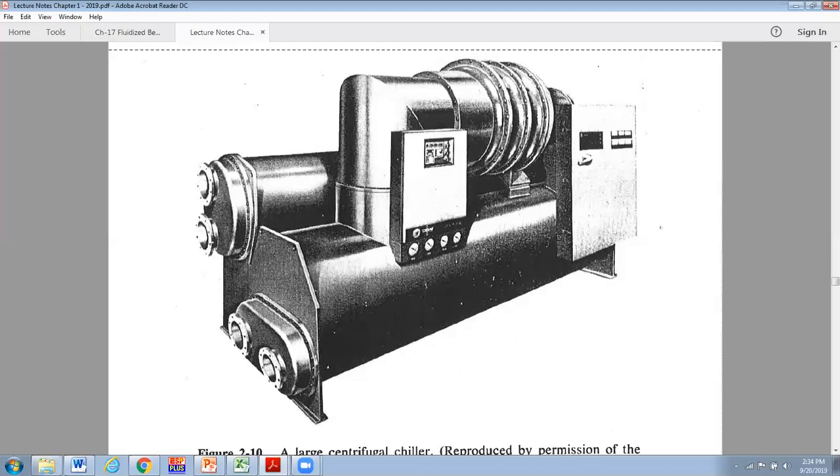And they're pretty good size. They can be really large. They can be much taller than a person. Smaller one, maybe not, 100 tons. The smallest centrifugal chiller, don't know exactly. I'm guessing someplace between 50 and 60 tons, probably. You don't see a lot of them. The smaller ones sometimes are for process use in industry. I would say typically 70 to 80 tons and up are what you see conditioning buildings. Much below that, it's probably going to be just what we call DX type equipment.